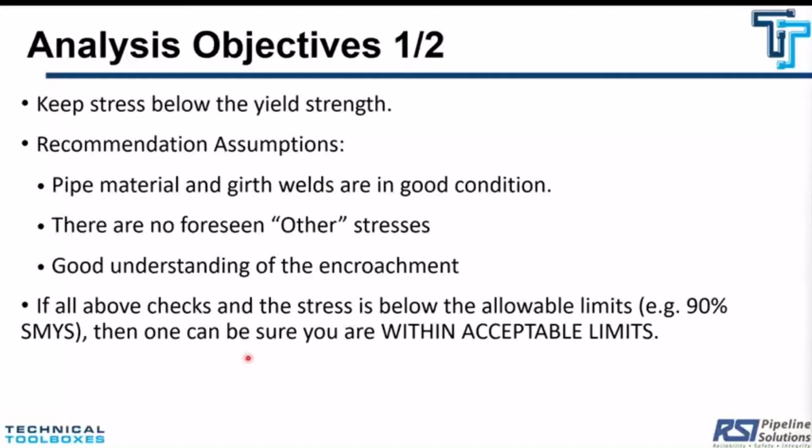So that's another assumption. If the pipe has features such as ILI features, such as metal loss or dent or cracking, crack-like features, again, they need to be treated separately, because the surface loading tool assumes that the pipe is free of such features, right?